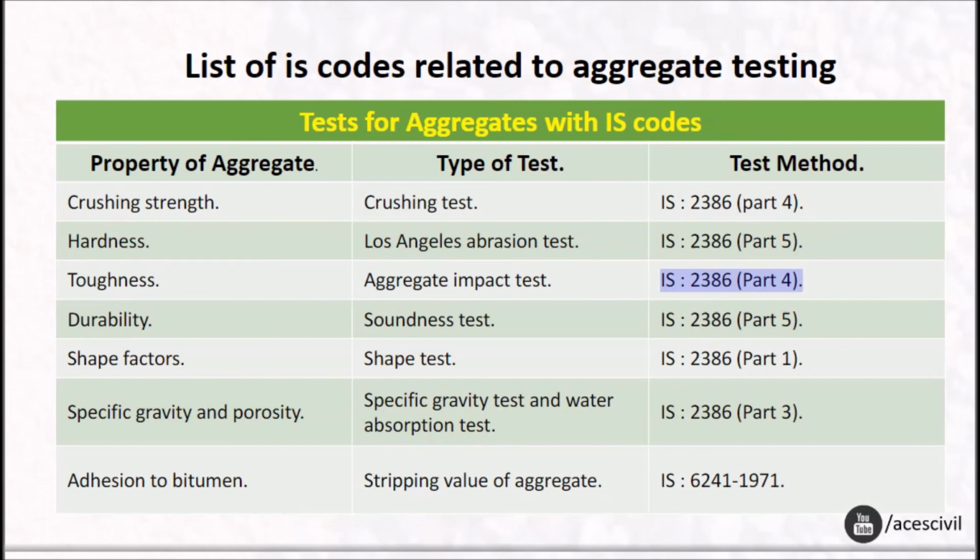IS 2386, Part 4. Durability: soundness test is IS 2386, Part 5. Shape factors: shape test is IS 2386, Part 1.